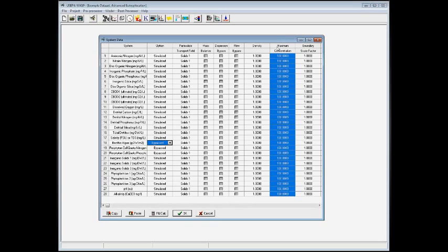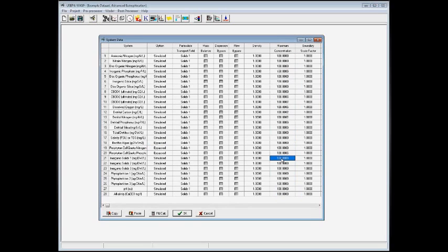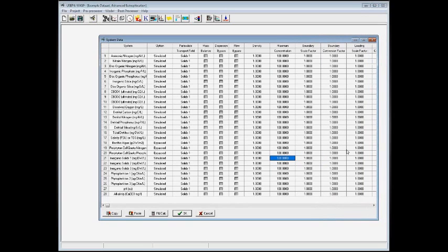So in the case here, if you were doing solids, you probably would want to increase this 100 to something larger, because it is possible to have a concentration greater than 100 for solids, so you would increase it, otherwise it would shut down. The scale factors that are out here to the right, we'll talk about later. You can also see them in another screen.